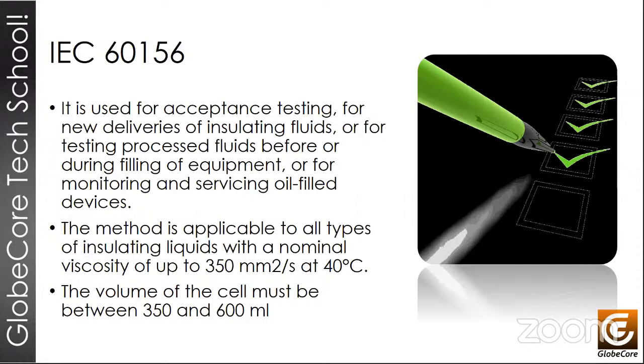Containers and the lids of the containers must be washed with a suitable solvent or clean oil to remove any residue left over from the previous sample. After cleaning, containers should be closed tightly and immediately and kept closed all the way until their use. And the removable electrodes must be stored in clean insulating liquids for protection.